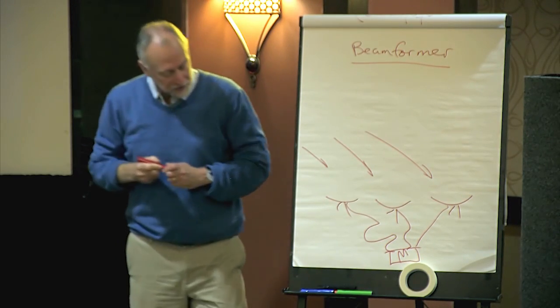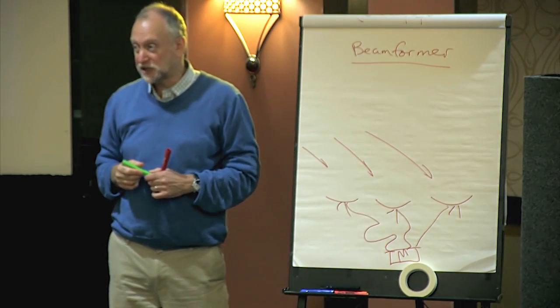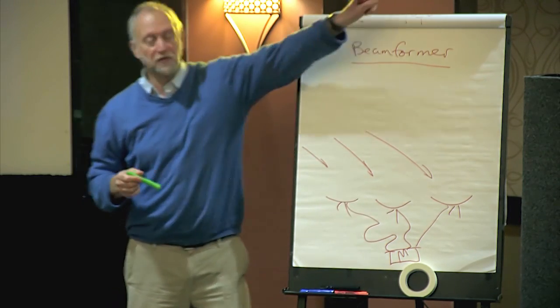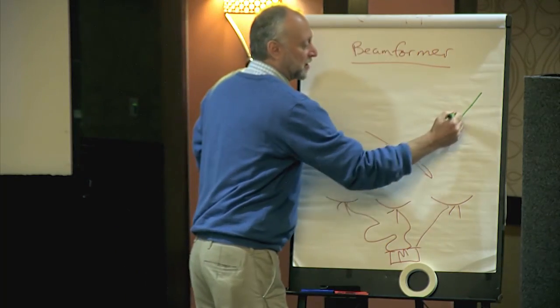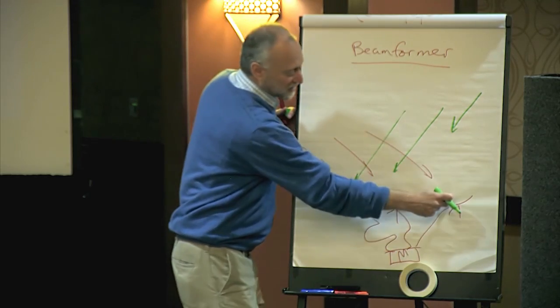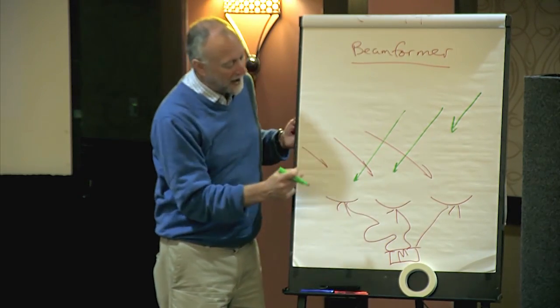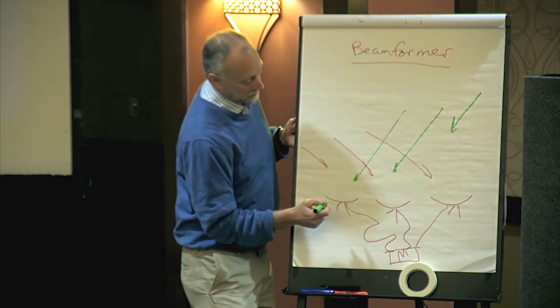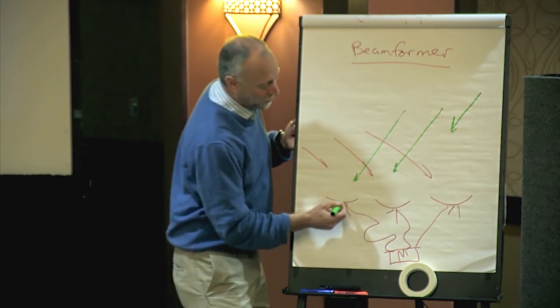But now suppose that I also simultaneously want to look over there. If there's a star over there, a galaxy over there, the light's coming in this way, it's going to hit this telescope first, and then this, right? So if I want to form that beam, I take those same 3 signals but have different delays.